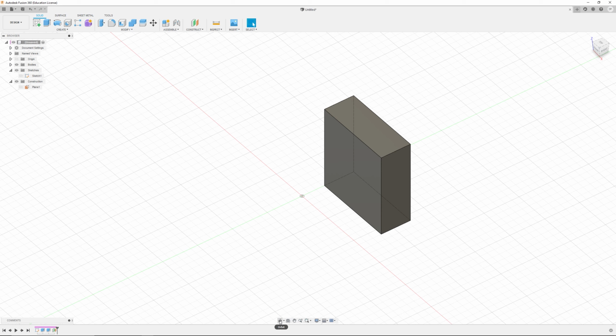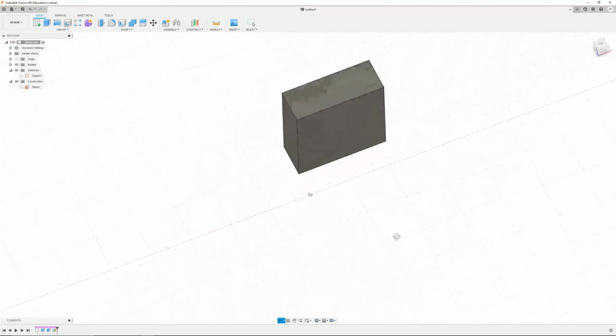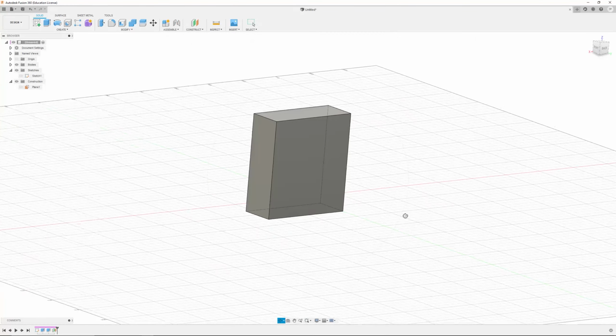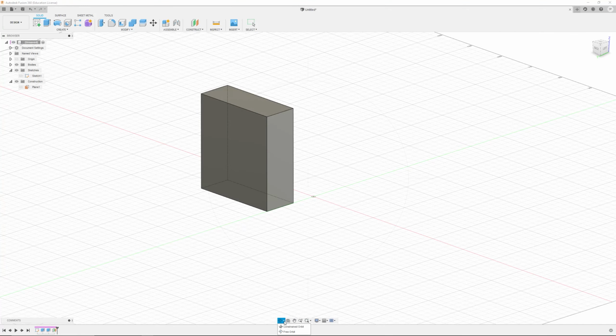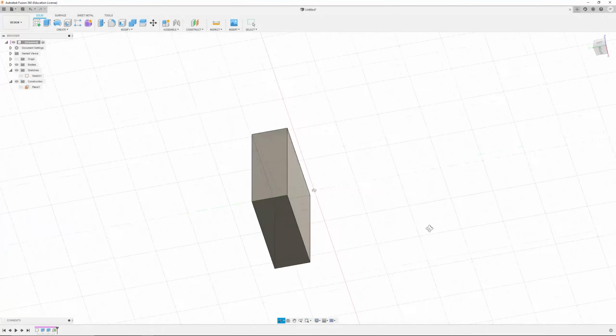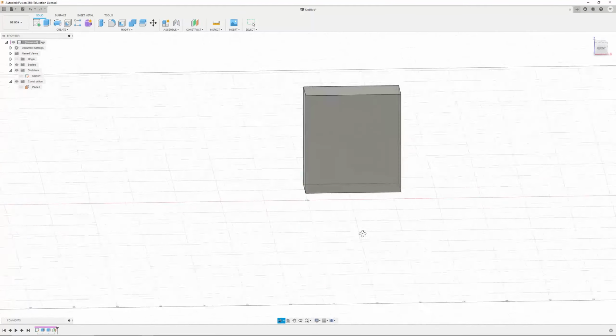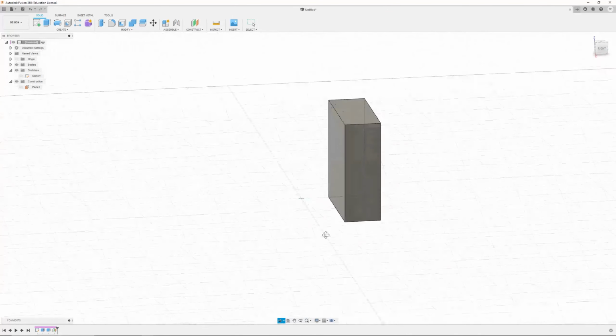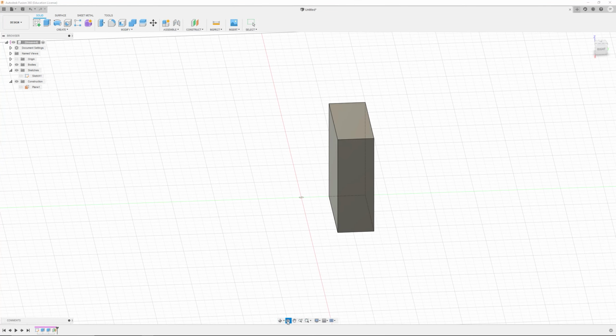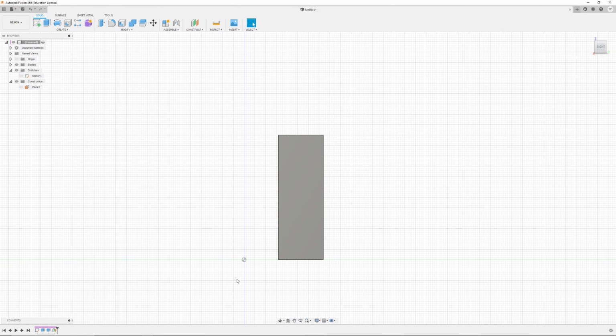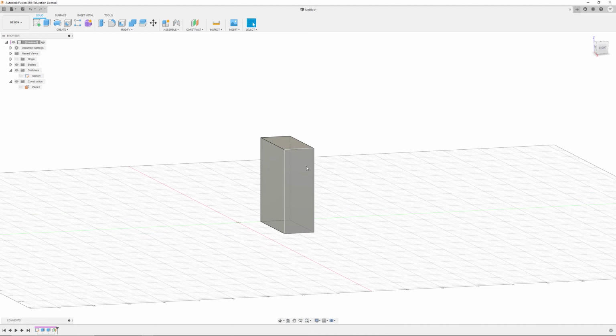Down here at the bottom, we have our view tool set. Initially here we have what allows us to select something and say if you want to be able to orbit, like so, and then I am clicking with my left mouse button here, or a constrained orbit, which is the default. What constrained orbit does is it tries to keep it flat relative to the Earth to give you a little bit easier time navigating.